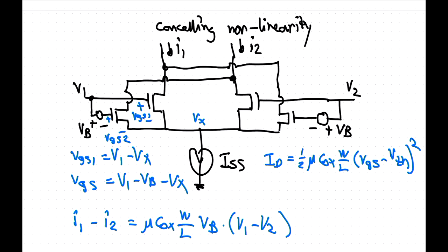Again, the advantage of this is that you can control the transconductance by controlling the bias voltage. So this is something you can do in a calibration phase, for instance. You can hook it up to a phase-lock loop or something like that and drive that voltage, so you don't actually need a manual calibration phase for that. So this is handy. You can drive that voltage. Admittedly, that is a floating voltage source, which you've got to make. So you have some restrictions on what you can do.